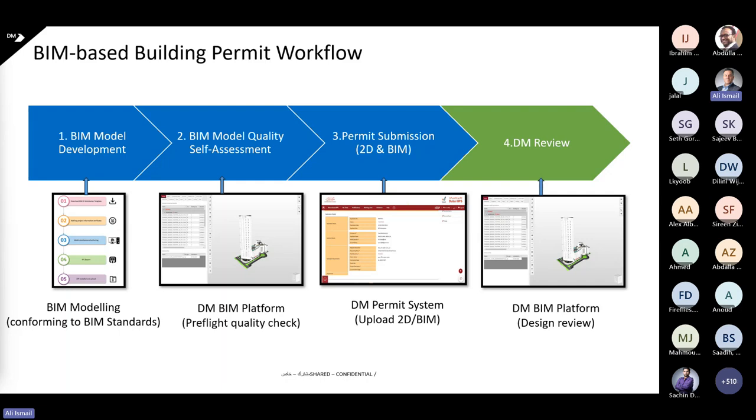Starting by downloading the standard, downloading a BIM template for Revit, ArchiCAD or Bentley, doing the design, including the information, until you reach the point that you export that model in IFC format. Then the next step will be to self-check the model quality.